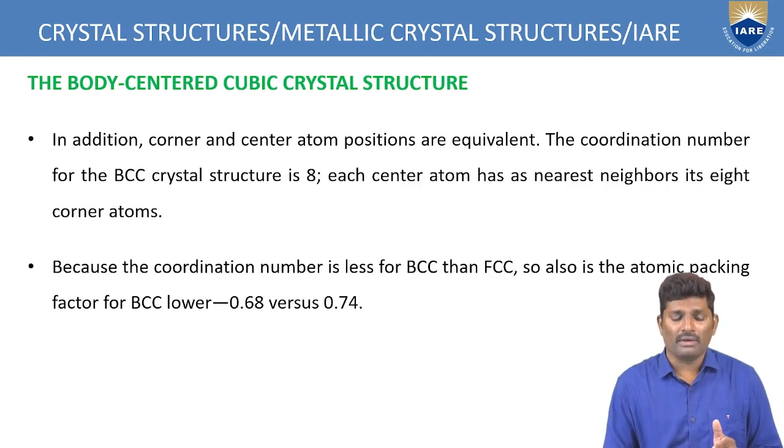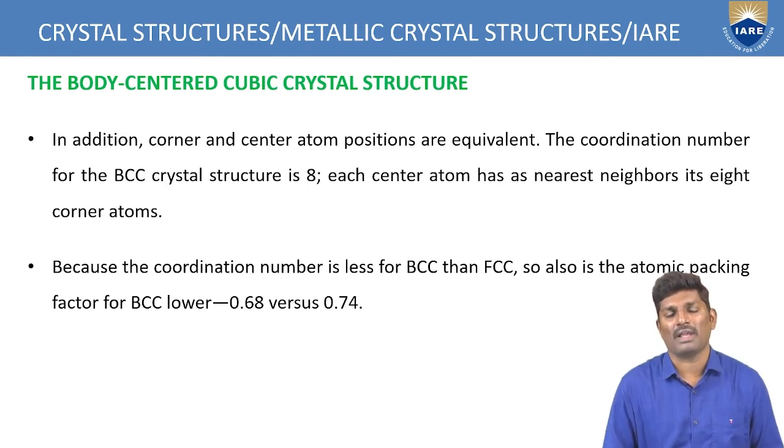And finally we have the atomic packing factor, which is 0.68. We are having a very low atomic packing factor when you compare with the FCC. FCC is having 0.74, that is the highest value, but the atoms which are having BCC phase will have a lower atomic packing factor value. That's why, again, in selection of material, one of the criteria is the APF, atomic packing factor value. So the elements which are having lesser values of atomic packing factor should not be taken into consideration.